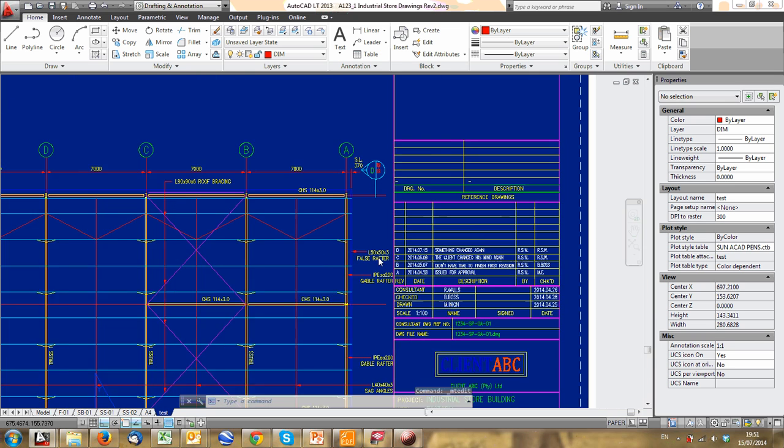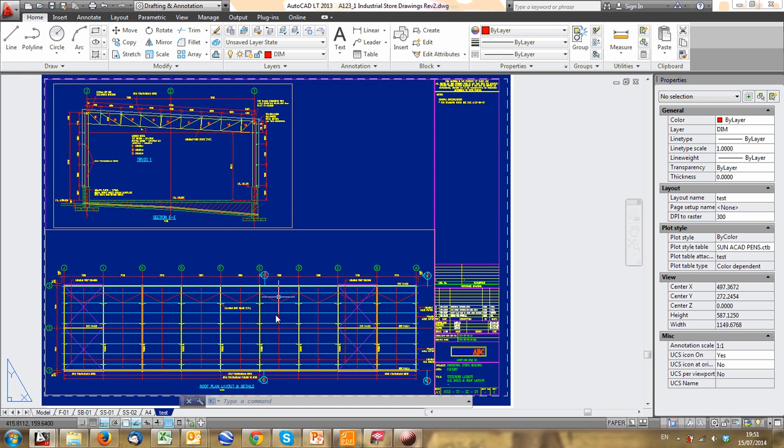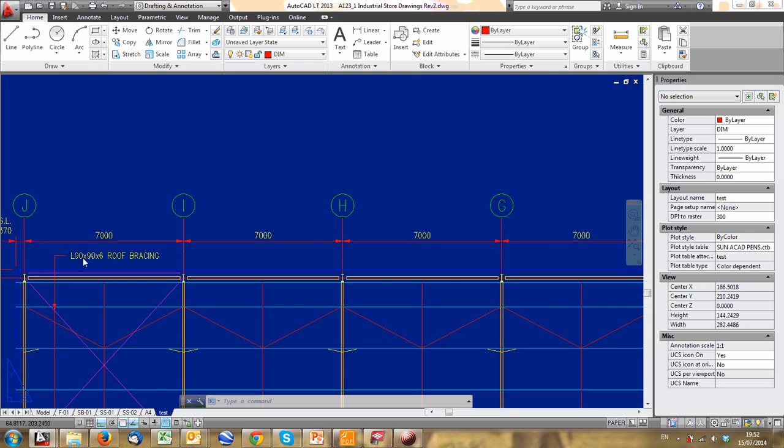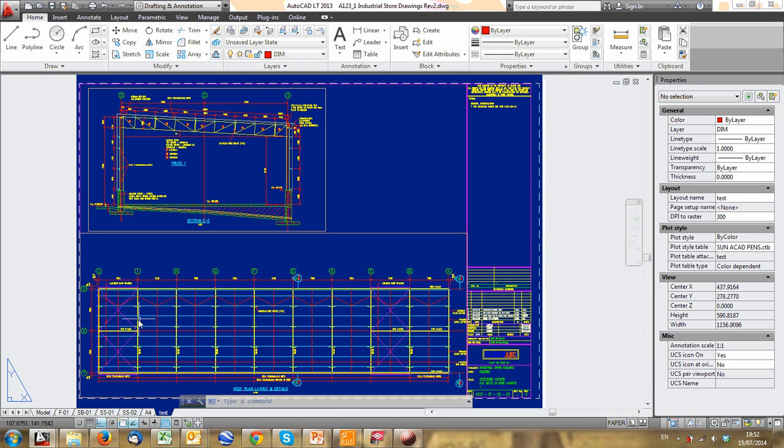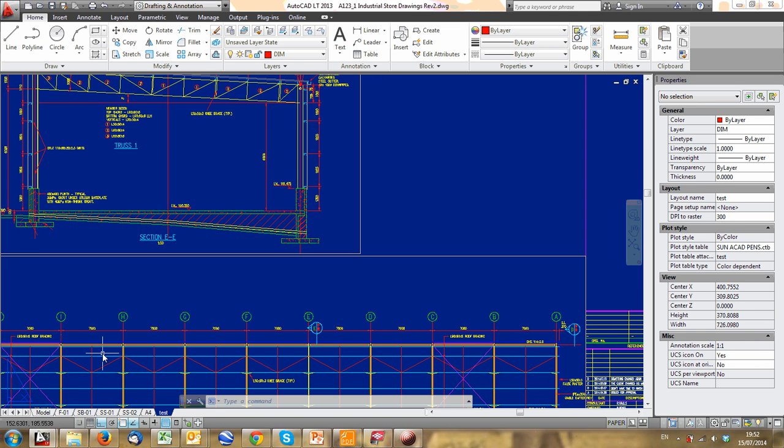Once you've done that though, it's also good to show on the drawing what changed. You can imagine, especially if a contractor is getting multiple drawings with lots of information on the drawing, he might not notice that this little note here has changed, and they could really be building that part of the structure, and he won't know till it's too late. So to avoid problems, you normally want to put a cloud around the information that has changed.